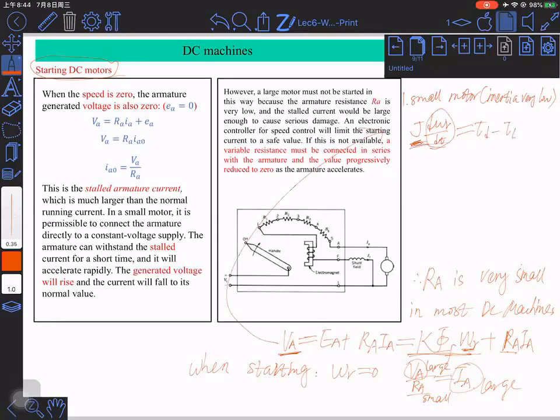speed because we have a torque developed, and because we have a very large current at the beginning, it gives us a very large torque, which is much larger than the load torque, then we can immediately accelerate the motor. And as long as the motor reaches a certain speed, we have a large enough Kφω_R, and this is going to consume a large part of the voltage, because this voltage subtracting Kφω_R divided by RA is going to be equivalent to IA.